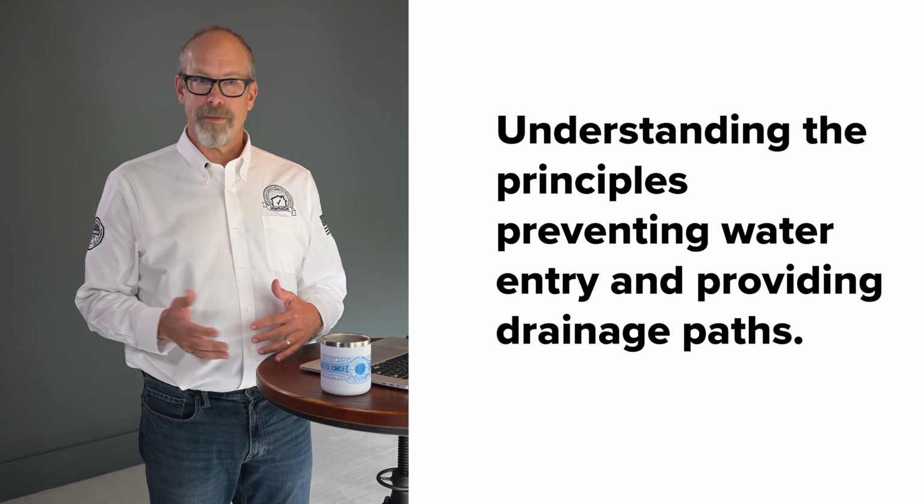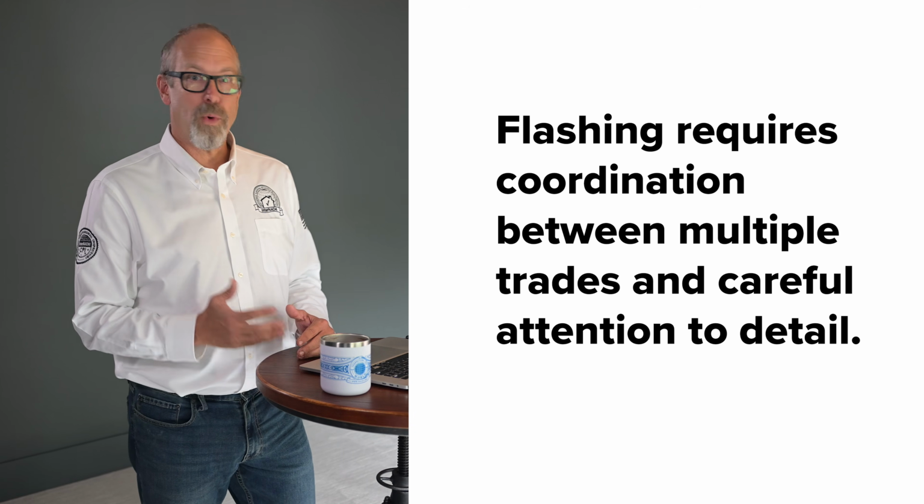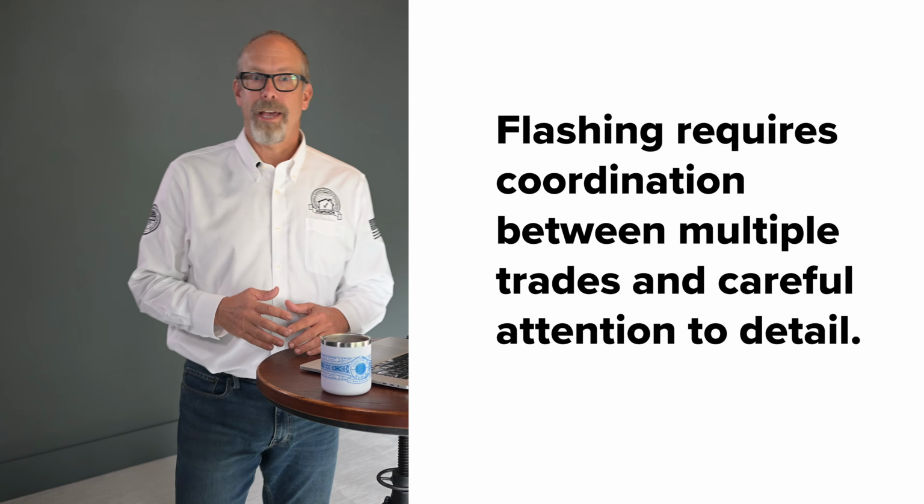Understanding the principles, preventing water entry and providing drainage paths, helps evaluate whether different installation techniques will be effective. Flashing requires coordination between multiple trades and careful attention to detail. Small installation errors can create major moisture problems, so your inspection helps identify these critical details before they cause expensive damage to wall assemblies and structural components.